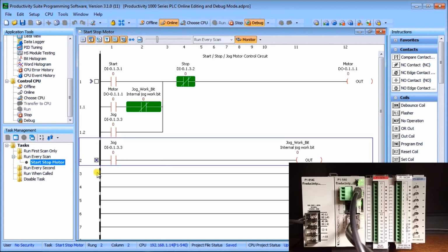And I can set up set points by hitting this, and it puts an X in the box. What that means is that I can now run to that set point, or I turn that off and it will continue. Up on my screen now I have, on my icons, a new set of icons that I've highlighted, and these icons here allow me to do different functions. Now I can highlight them, and the first one is execute outputs, which means that the outputs will actually be on as I cycle through.